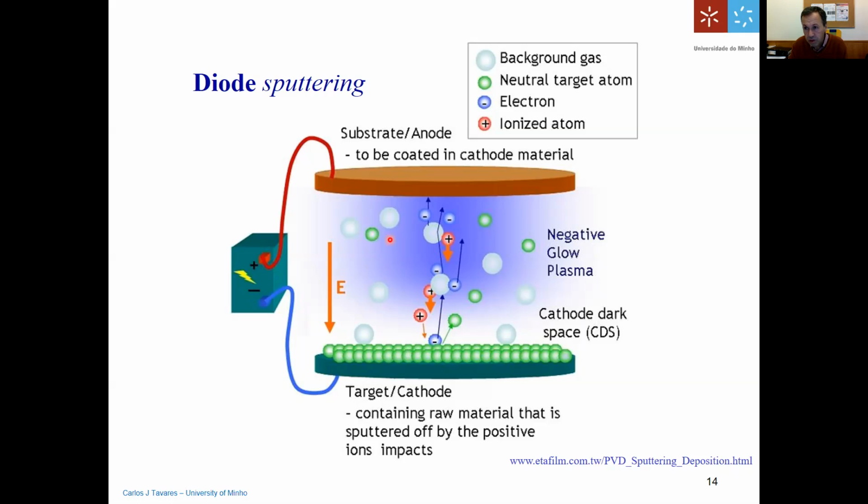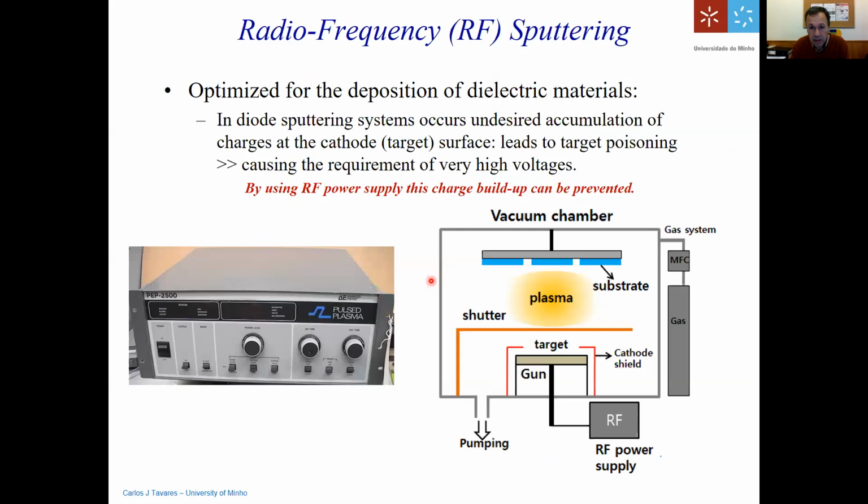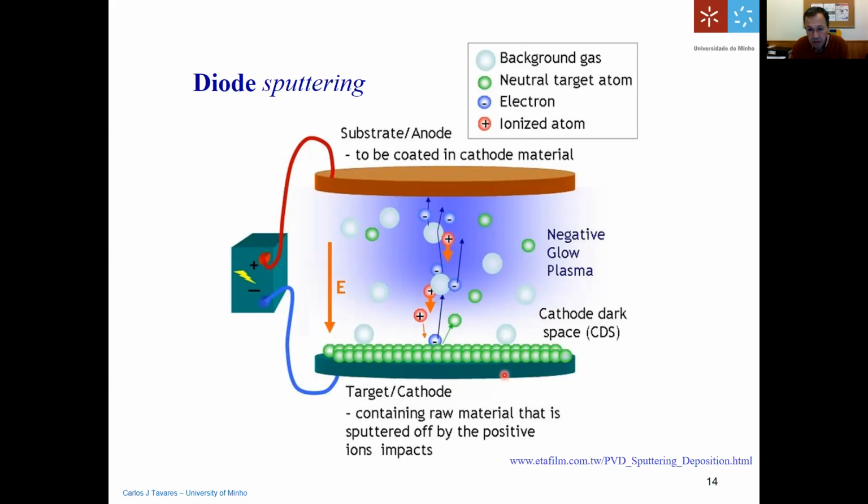So it's 6 orders of magnitude of pressure below what we would need before doing a sputtering experiment in one of our main equipments in the laboratories, okay? And so this is the easiest process, and you have an electric field between the anode and the cathode, and you can produce this kind of sputtering, okay? But this sputtering process is not very efficient. It requires higher pressures, okay?